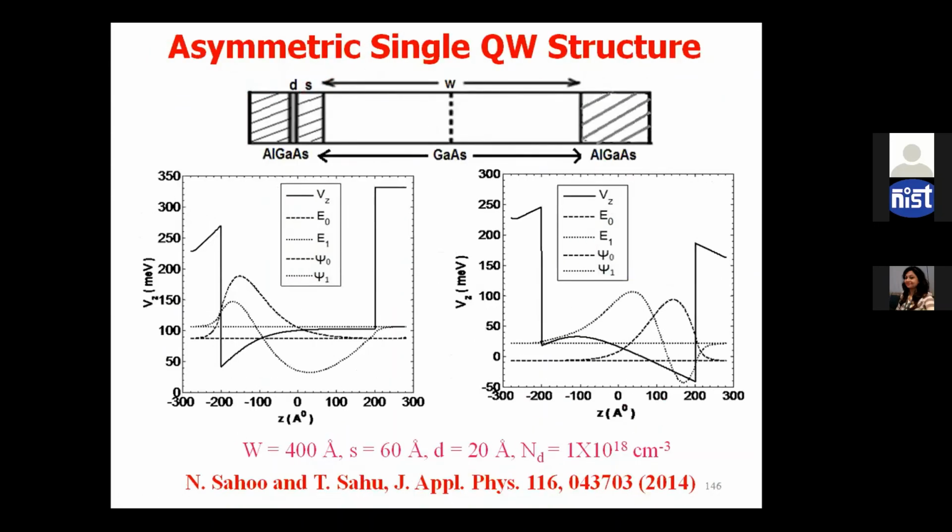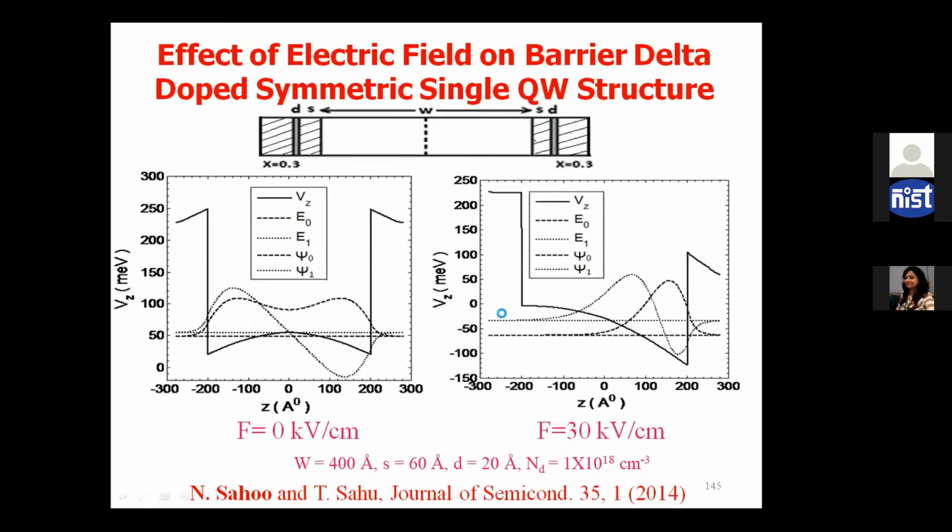This is in another paper. Here, instead of double side doping, we take a single side doping. If it is double side doped, no doubt the Coulomb scattering from the left barrier can be reduced here. But what about this right side? Because there is also doping on the right side, so there are positive ions. The dopants are on the right side, and now the distance between these dopants and this electron is very close. As it is very close, it can lead to reduced mobility.